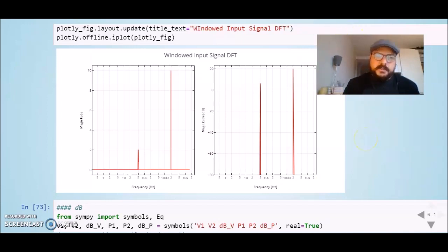And now we come to the dB scale. So we will take a reference of 1 volt. So we had an amplitude of 2 volts. In the dB scale, it will be represented by 6 dB. If we have 10 volts in the dB scale with a reference of 1 volt, we have 20 dB. So we can already see that there is a ratio of 2, so 2 volts and our reference voltage is 1, so we get 6 dB. And when we have 10 volts and the reference voltage is 1 volt, we have 20 dB.